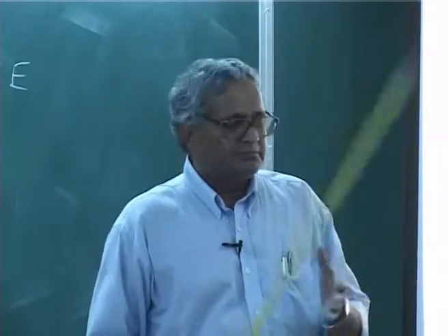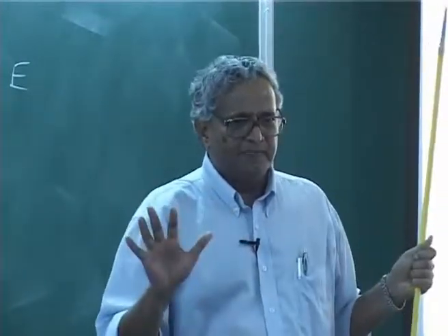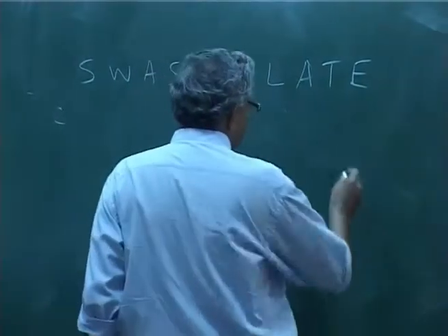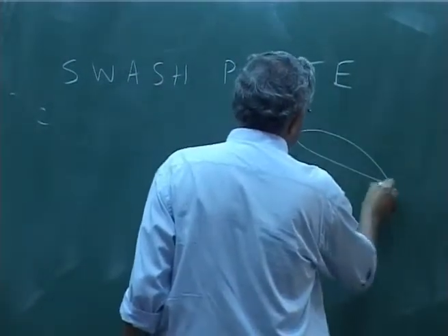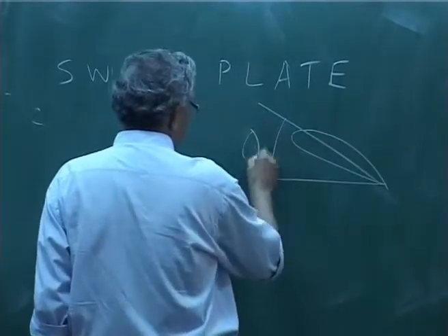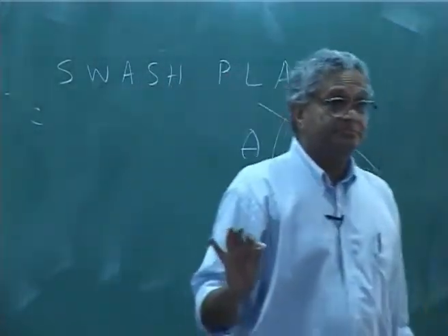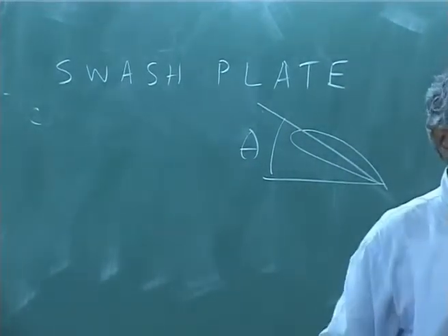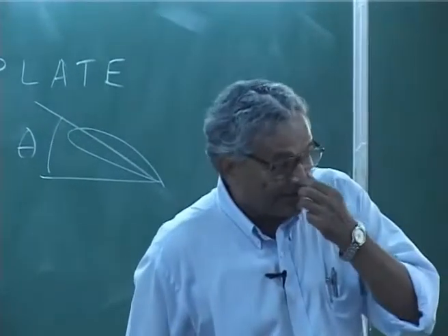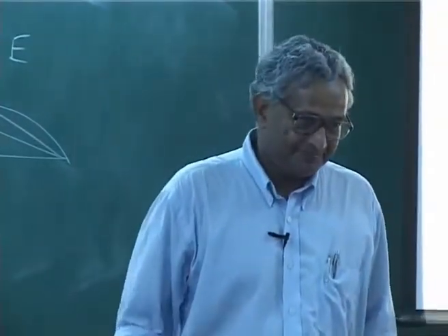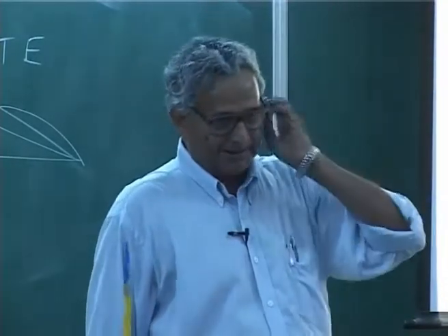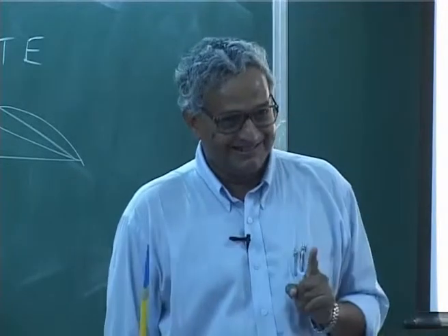Now the control to the blade is simple, because we are all from aeronautics, and we have only an aerofoil. What you can do at the most to an aerofoil is change the pitch angle of the blade, that is it, you have no other control. Now you may ask whether RPM is controlled. In big helicopters, RPM is regulated.